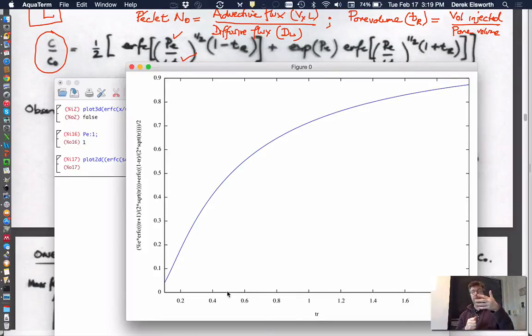When you are going through at a much smaller velocity and therefore larger dispersion, then you have these fingers, which is this mixing. And so when the first of these fingers arrive, then it's kind of a dilute concentration. I guess this isn't in space, this is actually in time. So as soon as it breaks through, at 0.4 pore volumes, it's come through at a concentration of 40%. At 0.6 pore volumes, it's come through at 55% concentration.